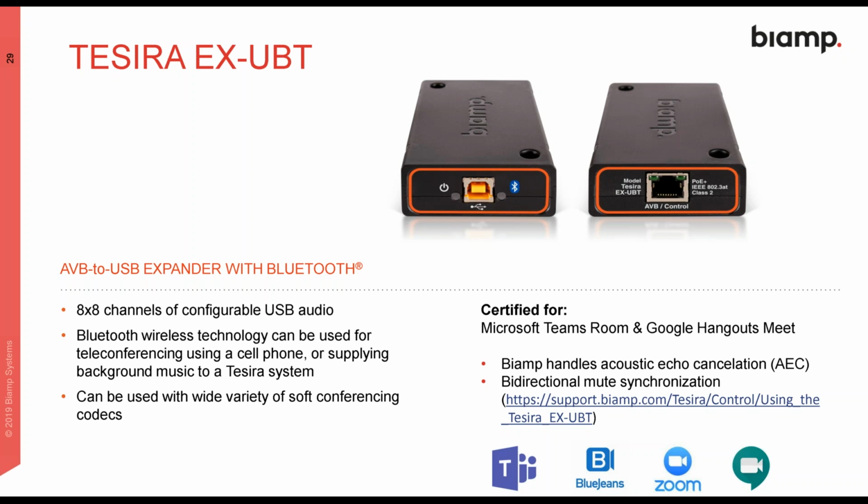What does this mean? It means that when you're using a Microsoft Teams Room system or Google Room system, if you're not using a certified DSP, then if you have a mute button on your mic, you can touch it, it will mute your mic, but it will not reflect the muted state within the conference, within the codec.